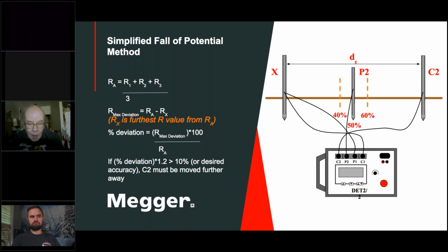But what about if you're testing a grid? Well, in many cases, that grid may be connected at every corner back to your electrical system. Or what about a tower ground with a ring around it? Typically, the guy wires are connected as part of the grounding system. So now what happens is you clamp onto a convenient point and you energize the tester, but now your test current finds a short circuit.